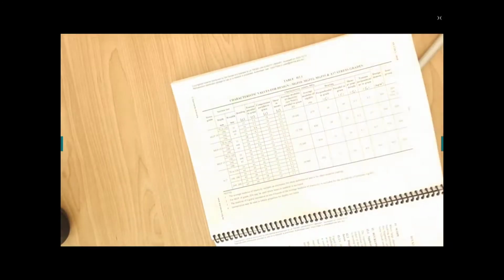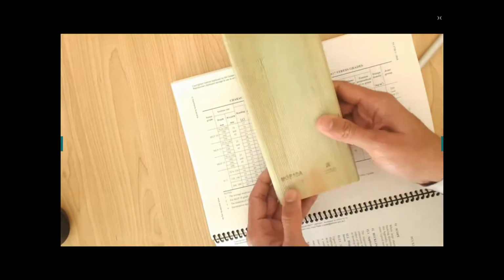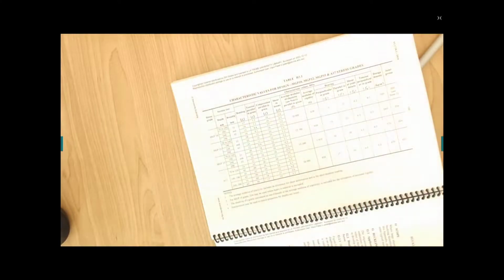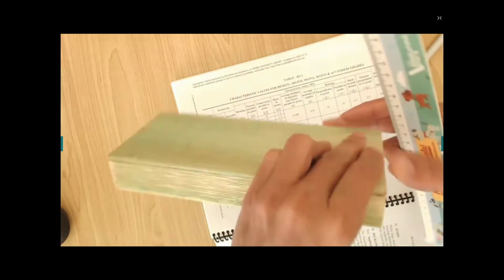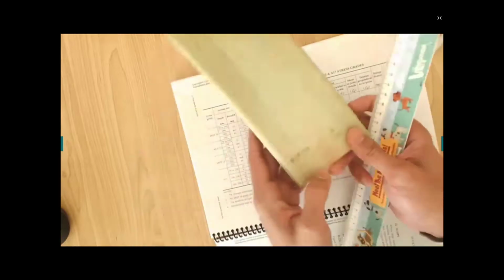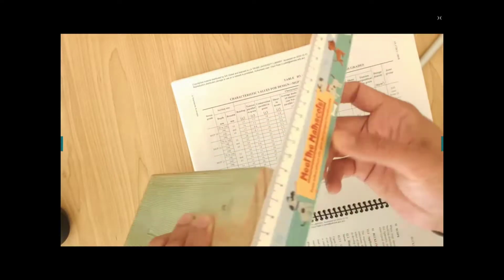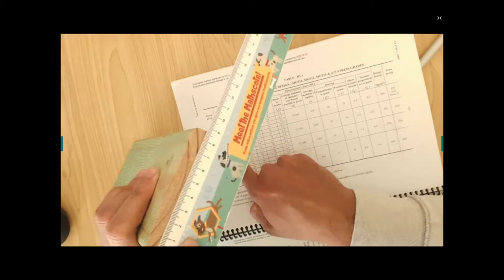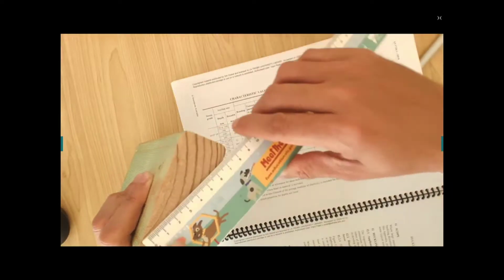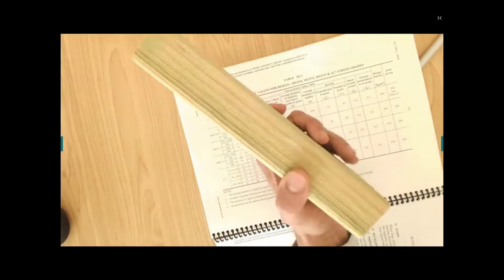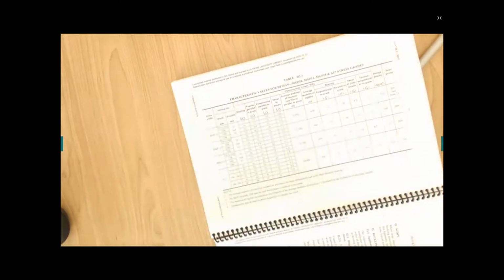MGP 15, I have, by the way, the timber. I'm not sure what grade you have. I can see MGP 10. Can you read it, right? You can see MGP 10. I'm not sure what the size is. So it's MGP 10, right? Softwood framing has 12. Yeah, MGP 12. And what is the size? The depth is about 70 to 140, about 85, yes, here. And the width is about 35, yes, 35. So that's quite reasonable. You have seen this kind of timber, right? In Australia, we have this kind of cross section. So that is MGP 10, and these are all the properties. I hope you understand these 10, 12 and 15 configurations. All right, continue.